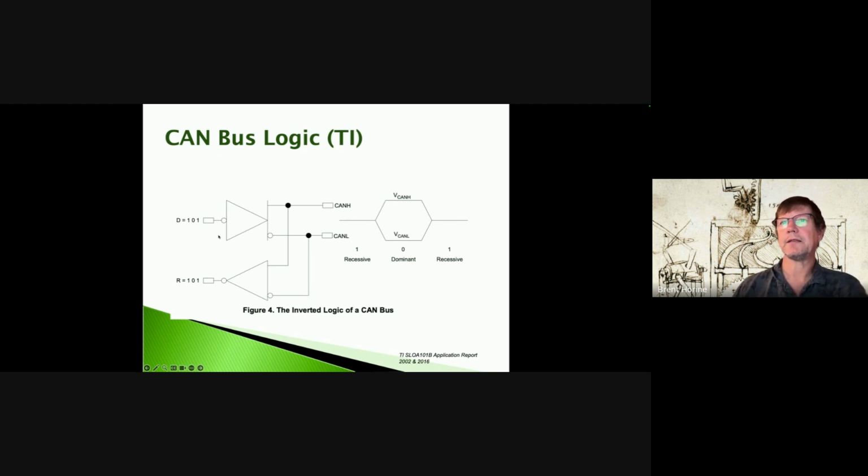So we're going to pull the bus low. There are some pull-ups in here, but the other thing to note is that we transmit onto the bus and we simultaneously listen. So this node is listening to the bus while it's transmitting, and that's important to help us do the arbitration, and actually the collision detection part of the arbitration. So we're listening, and we can hear if someone else is talking also.